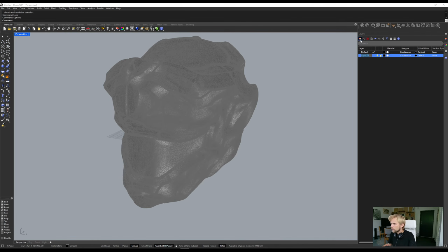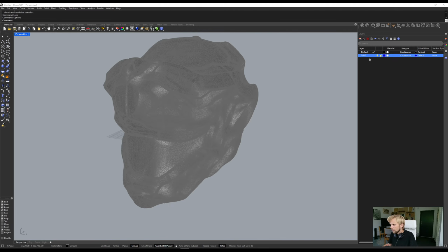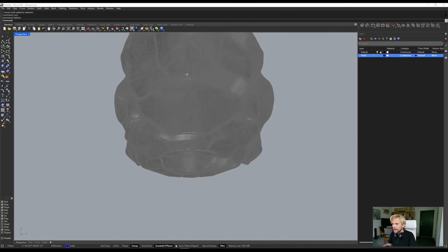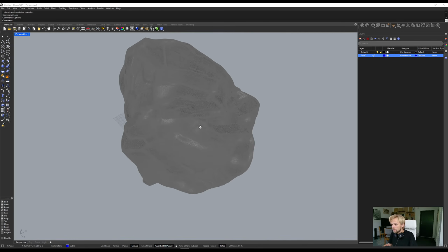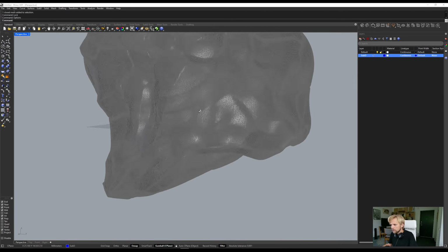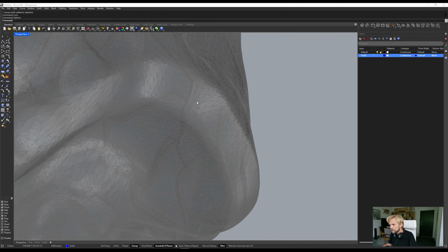Now I'm just going to create a new layer, call it sub-D, like that. Make it, I don't know, blue, I tend to use the blue color for this, make it active, and we will create a single sub-D face somewhere on this mesh. So it doesn't really matter where we start. I guess we can start here on this edge right here.